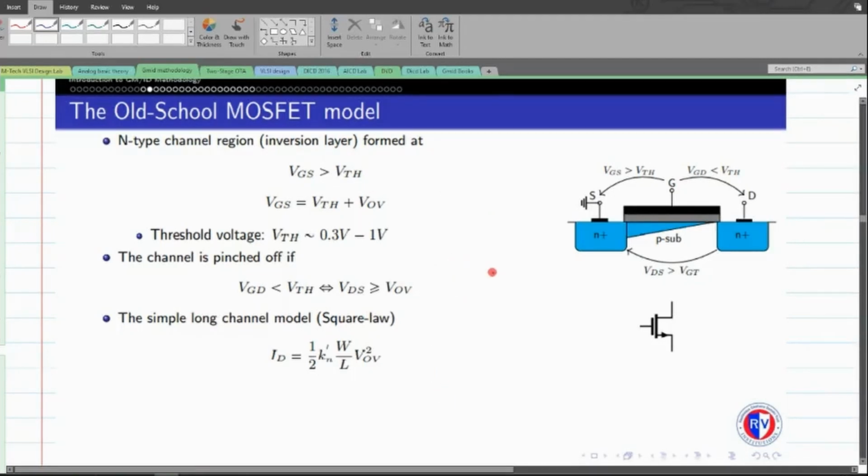For a transistor to be in the saturation zone, there are a few conditions that we have to satisfy. The very first thing is that the value of VGS is supposed to be greater than the value of VT. The second condition is that the value of VDS, for an NMOS, and this is all with respect to the NMOS transistor, can be either greater than or equal to VGS minus VT. In general, this VGS minus VT term can also be rewritten as VOV, or the overdrive voltage. We generally want this condition to be satisfied.